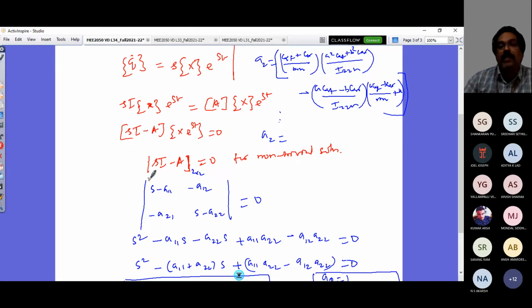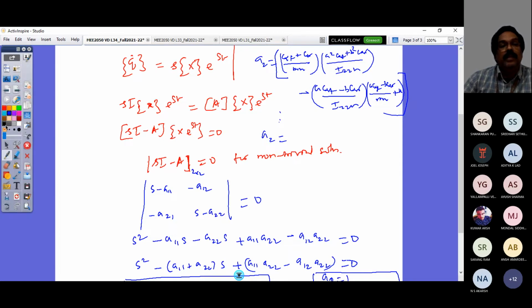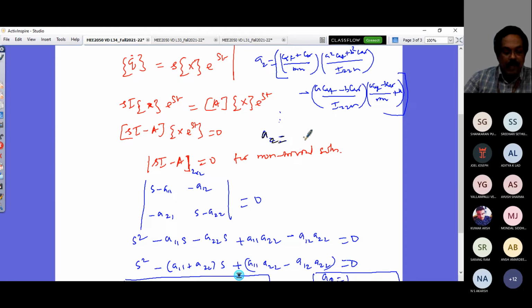Finally, you would see that it would appear like this. So this A2 would be equal to 1 plus m into (B C alpha R minus A C alpha F) by L squared C alpha F C alpha R into U squared.